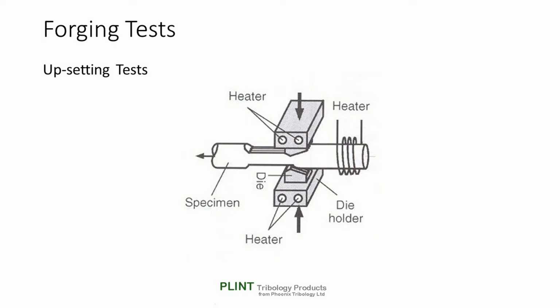A range of heated upsetting tests have been used to model hot forging processes. These tests typically involve drawing a preheated rod sample through a die tool in much the same way as with a standard draw strip test. It's not clear whether anyone has thought of adapting the test to provide a similar method to the roller bead test.